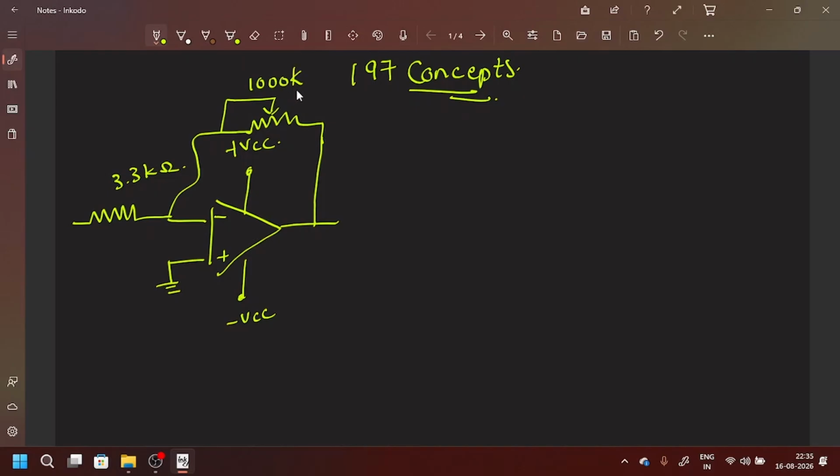So the circuit that I'm showing you here is limited to Proteus itself, because Proteus is not able to do the initial calculations or the initial triggering of the circuit for the oscillators. I am increasing the feedback resistor value so that this resistor can create a huge load onto the op amp and simulate the trigger situation for the software to recognize that and generate an output. Okay, so I'm going to take up a potentiometer here of 1000 K, and since this is the output,